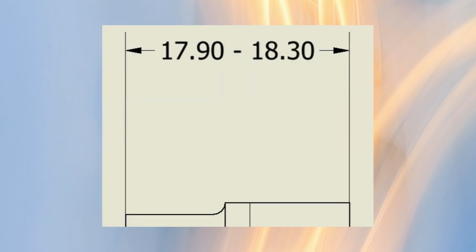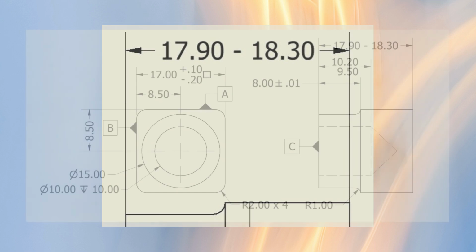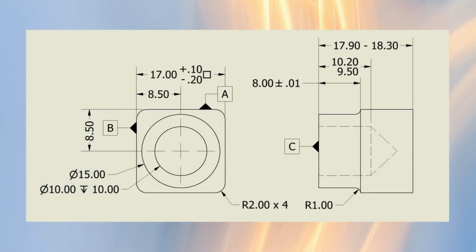This example is similar to the previous one, giving us the lower and then upper limit. We would derive the nominal value in the same way, as halfway between. It is only the layout that differs. We should now be able to read all the information needed on this drawing. It should be noted that it is rare to find one drawing with lots of different tolerancing styles. Most authors of a drawing would stick to only one or two methods for simplicity.